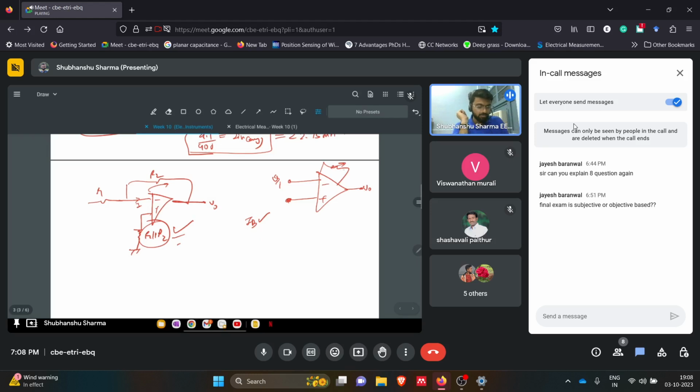Then we change it so that this V naught becomes zero when we are giving no voltage to the input side of this operational amplifier. I think this potentiometer is connected in the input side, and we change its setting so that the output becomes zero. That is the simplest way of removing that offset voltage.